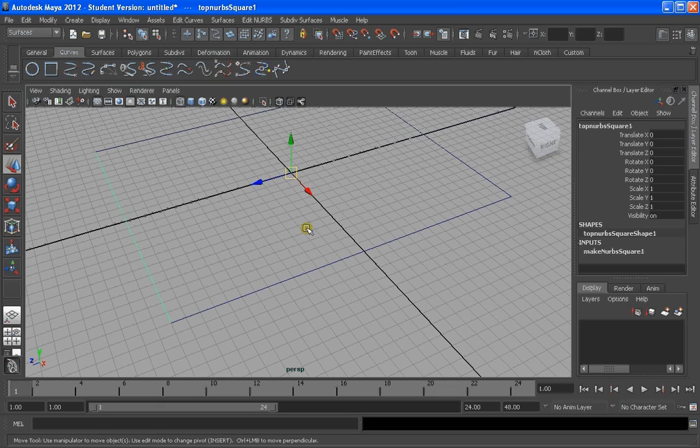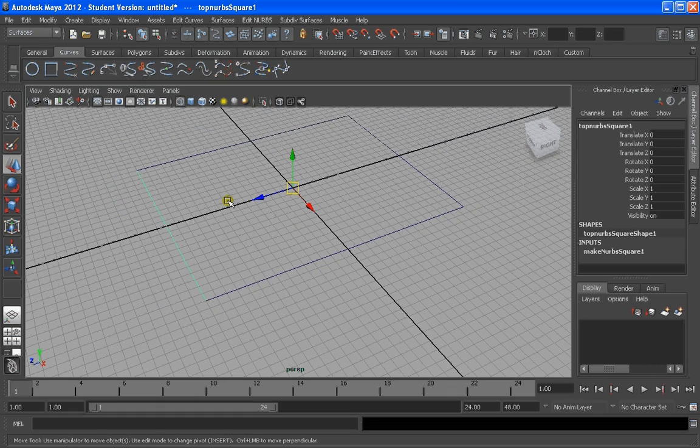I'm pressing W. It sets in the middle because it's the center of the rectangle, and we have to move the gizmo here. For that I'm going to press D. Let's remember D to move the gizmo around, and I want to attract it to the curve. In that sense we have to press C as in Charlie. It's kind of tricky to snap it to curves. You first have to put it close to a curve, and then you have to move it along the curve with the same two buttons, D and C in this case.